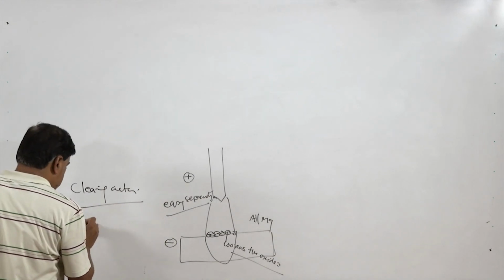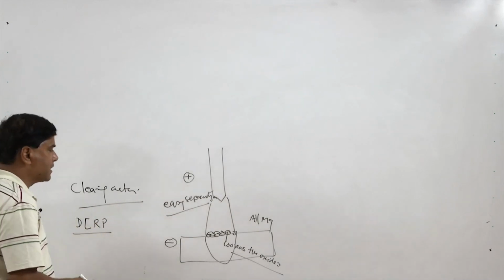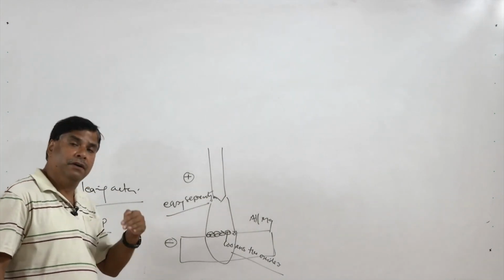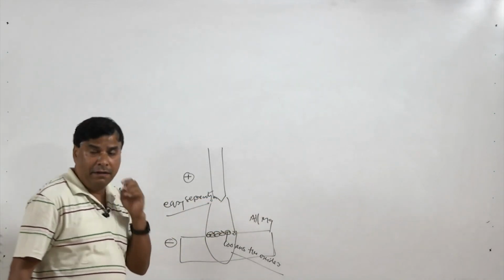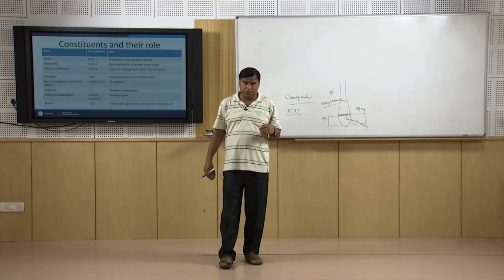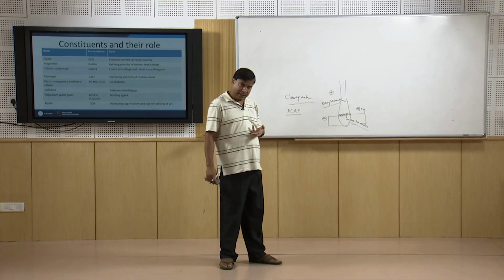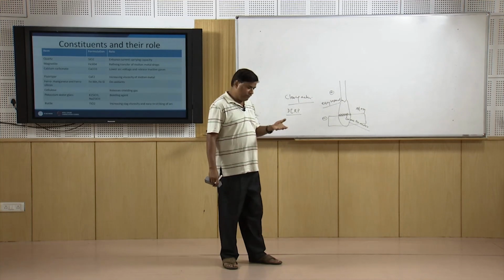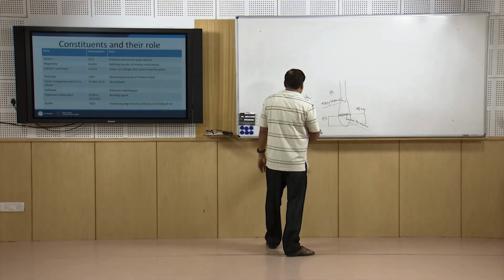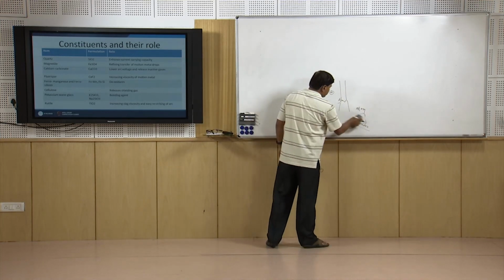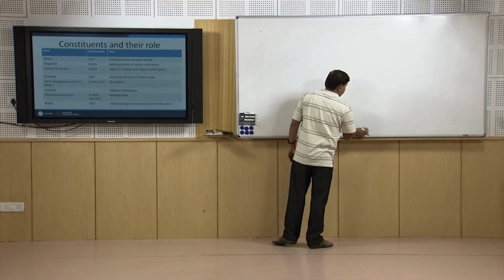So the use of DCRP is intentionally used sometimes to exploit this concept of mobile cathode spot formation, especially in aluminum and magnesium welding, because the formation of the mobile cathode spot helps to loosen the oxide layer, and the loosened oxide layer starts floating over the surface of the weld metal and thus can be separated easily, which in turn will help to clean the weld and produce cleaner weld metal.